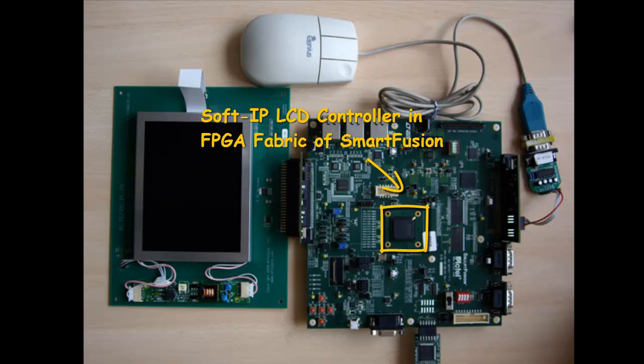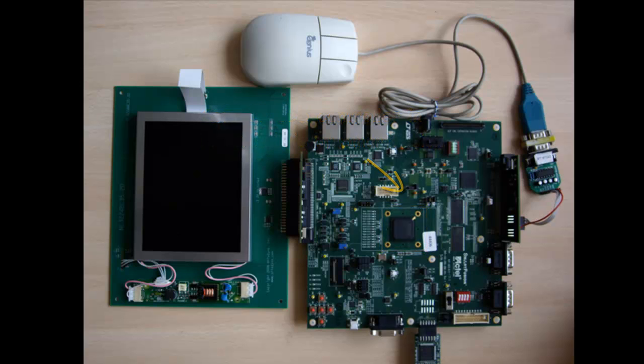SRAM. Another block of the LCD controller IP retrieves the pixels from that FIFO, converts them to the format required by the digital TFT LCD interface, and feeds pixels to the LCD module at a 5 MHz rate. In other words, the LCD controller IP implements a graphical interface coprocessor engine that runs in parallel with the Cortex-M3 processor core. From the software standpoint, when a pixel is written to the video frame buffer, it is immediately displayed without the need for any further involvement from the main CPU. The LCD controller IP is configured to support 240 by 320 resolution using 16-bit pixels in RGB 565 format.